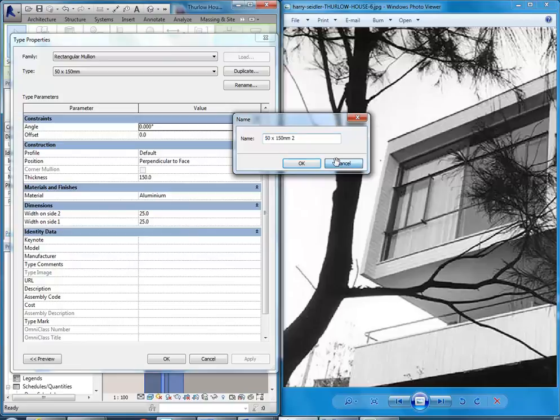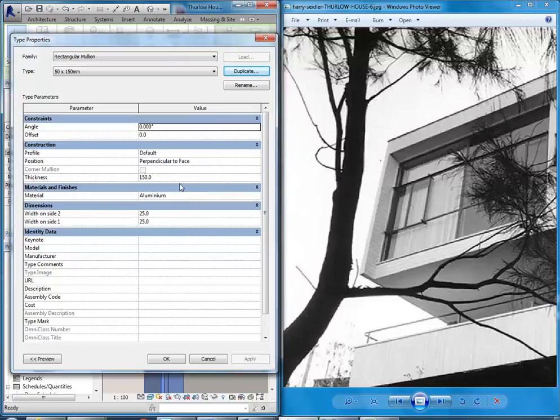No, it's not highlighted. So you need to make sure you've got the mullion. You don't have the mullion selected, that means. Yeah, I do. I have the whole window frame. Then you've got to go to Filter. Yeah, and you've turned off everything except for the mullion, and I still have... Just give me a look. Yeah, no, go back to Filter. Yep, and okay, just go to Check None.